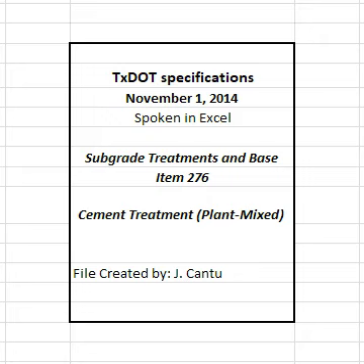4.1 Mixing. Thoroughly mix materials in the proportions designated on the mix design, in a mixing plant that meets the requirements of Section 276.3.2, Mixing Plant. Mix at optimum moisture content, unless otherwise directed, until a homogeneous mixture is obtained. Do not add water to the mixture after mixing is completed unless directed. The engineer may sample the mixture to verify strength in accordance with TEX 120E and adjust cement content to achieve the target strength for work going forward.